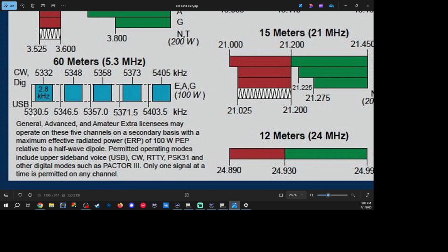So we want to have this number, and if you want to label it with the center frequency like Yaesu did, you can have that number. So we're going to do the voice memory channel and the CW memory channel. We're going to start with channel 1, go through channel 5, and put these lower edge frequencies in for voice first. So let's go to the RT Systems software.